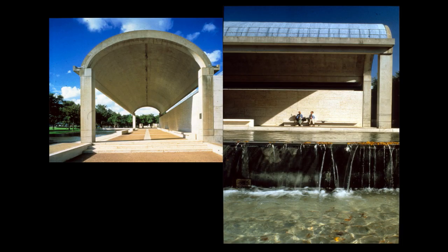These are made of poured-in-place reinforced concrete. They consist of piers at the four corners of each of these units, horizontal beams that run down the length of these units, supported by the piers, obviously. And then on top, we've got something that is not exactly hemispherical, it's a little depressed. It doesn't rise quite to the height of a hemispherical vault. And furthermore, it is not a structural vault. A structural vault is going to have each and every part of it in compression.